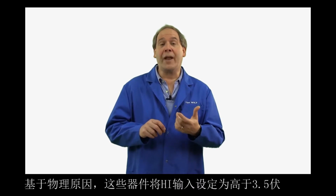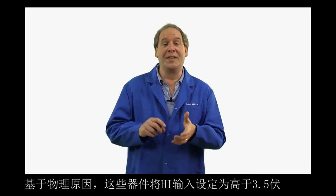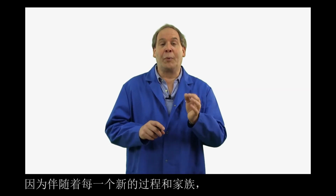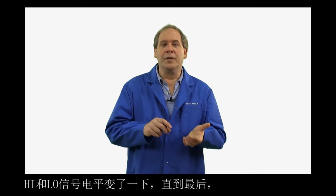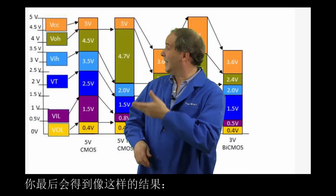But then along came CMOS logic, and for a variety of physics reasons, these devices interpreted high inputs as anything above 3.5 volts and low inputs as anything below 1.5 volts. See the issue here already? As each new process and family came along, the high and the low signals changed a bit, until finally you ended up with something like this.